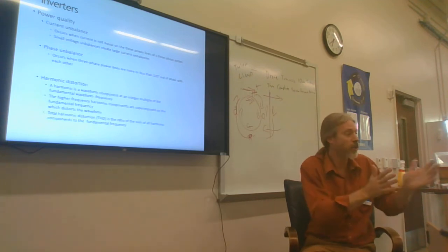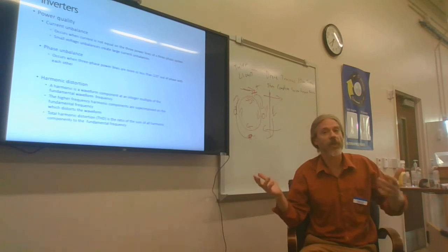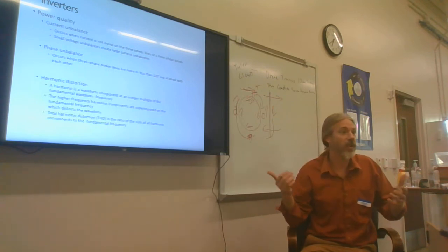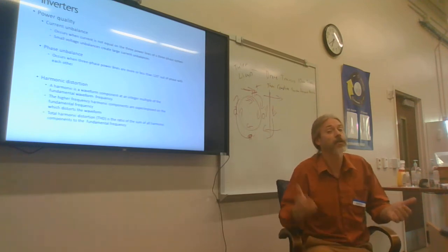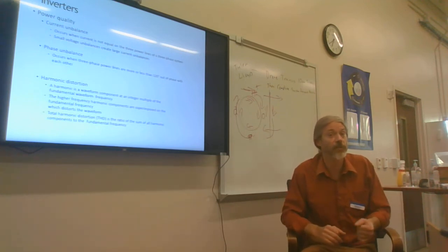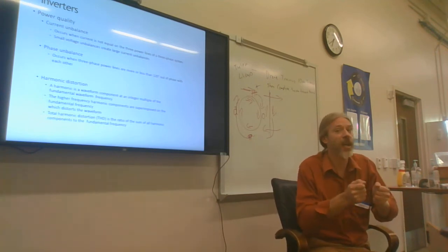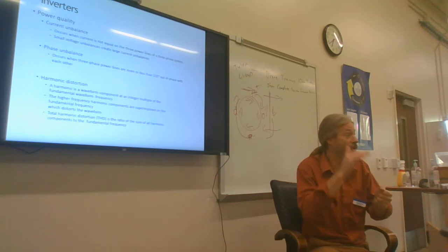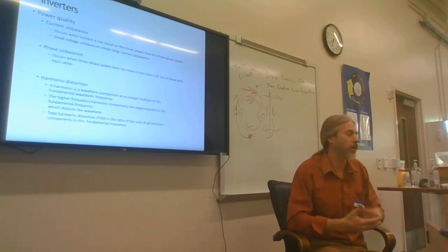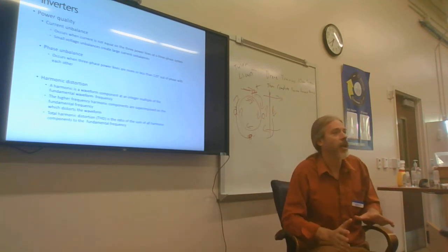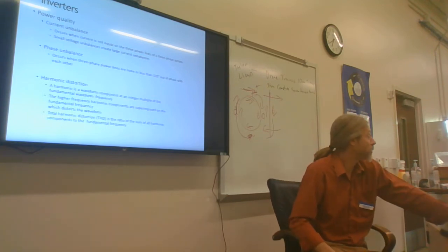Phase 1 and 2, phase 2 and 3, phase 1 and 3, phase 1 and 2, back and forth. I mean, I'm human. My timing gets off. Timing on inverters can get off also. A lot of times, phase imbalance can be solved by turning all of the inverters off, disconnecting them from any existing power sources, de-energizing them to where there's not even stored power, and then starting them back up. Almost always, that will fix the problem. If not, it's probably going to be a warranty issue.